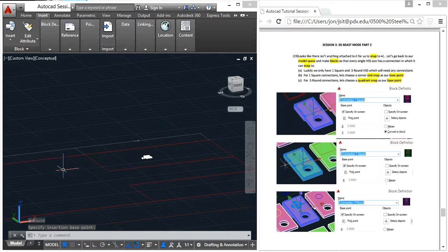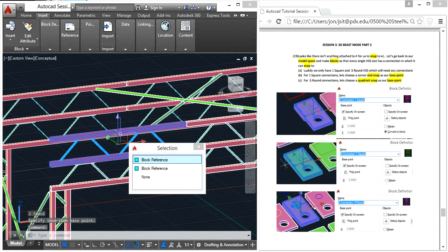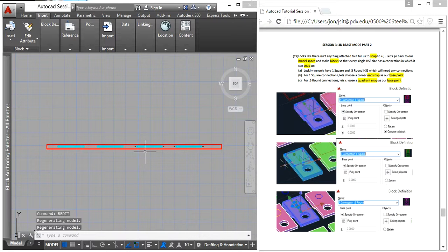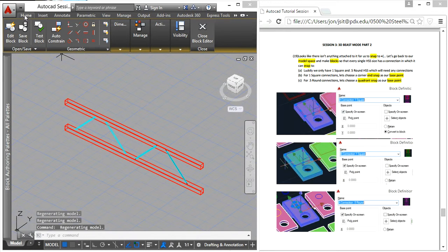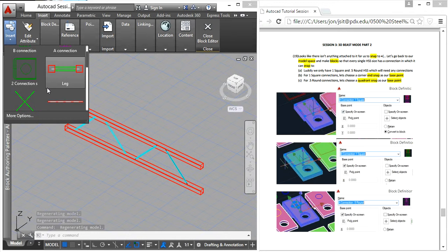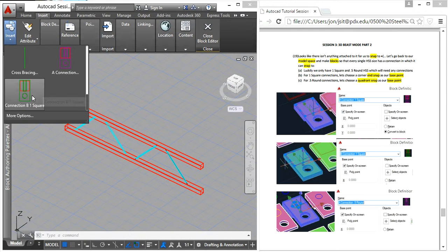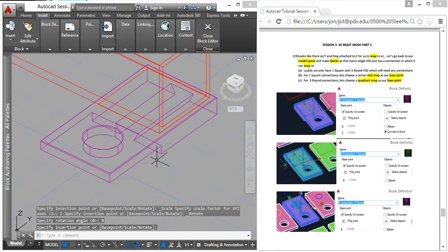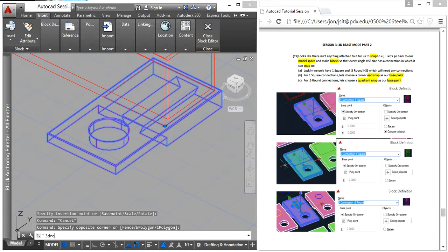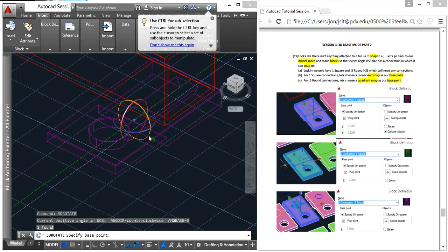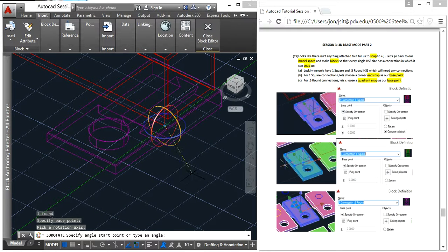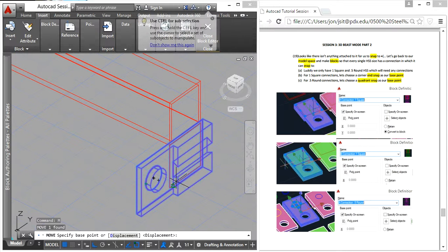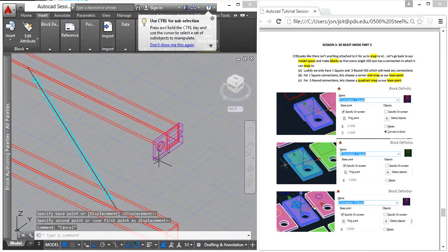Now let's go back to our end top decking. Set it, not bend it. Enter. Okay, let's get into our 3D view. Go to Insert, go to Block, and scroll down, and you'll notice that you have your connection here. I need an A connection, so I'm going to insert it there. I need it rotated, so I'll hit 3D rotate, and I need it so it can go right on the face. Let's pick that one. Ortho on. Bang. Now let's move this whole thing, snap to that snap, and let's make a copy of that.